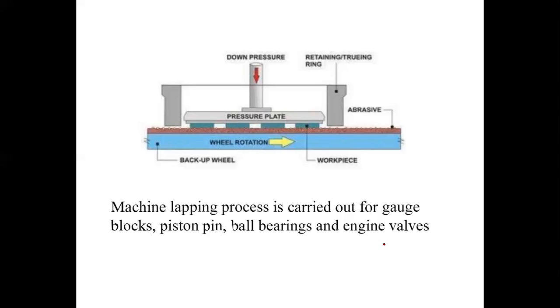That's why for the piston cylinder motion in an IC engine we need super finishing, so that the cylinder and the piston perfectly match and there is no gap, not even micron level gaps. Even with micron level gaps, the compressed gas in the combustion chamber, instead of forcing the piston down, can escape through the gaps between cylinder and piston. To avoid this, the piston and cylinder need very good surface finishes. We give those surface finishes using lapping or honing operations.